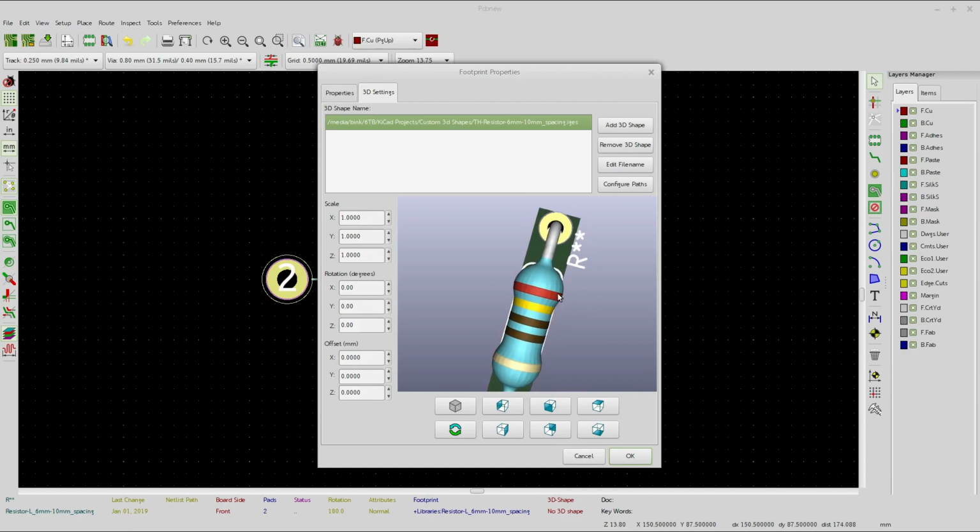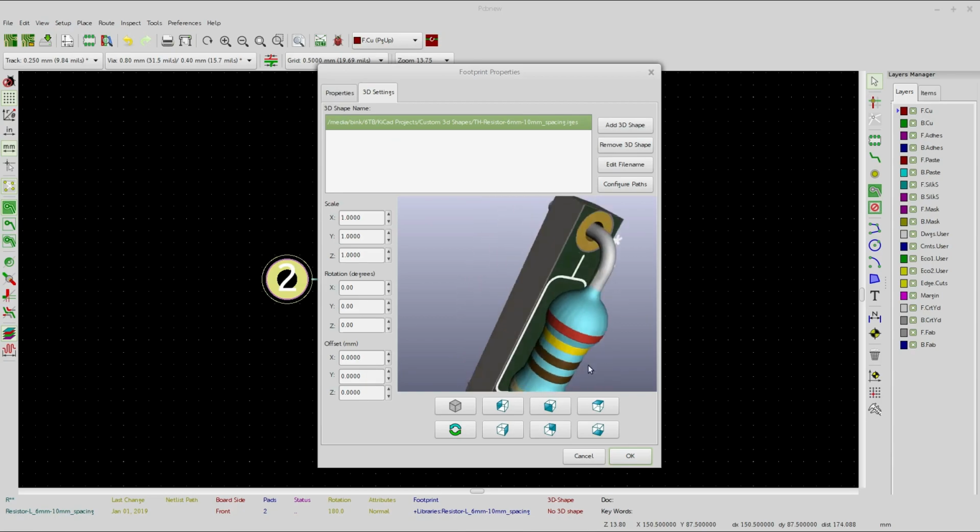I could have increased the diameter a little bit there, you see? Or of the footprint itself, so I don't inadvertently stick something too close to this, because if I put another resistor right smack up against there, they're going to run into each other. Let's go fix that.